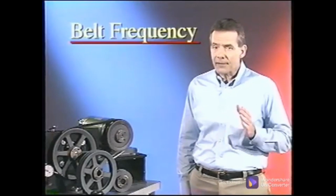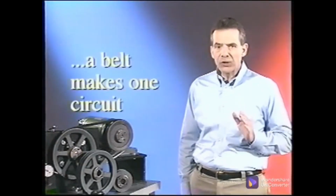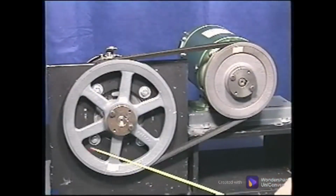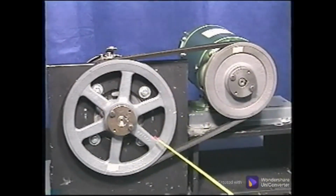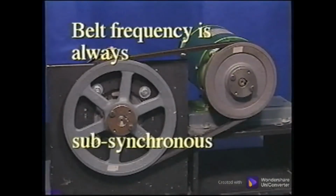This belt rotational frequency is usually referred to as belt frequency and can be defined as the number of times per minute that a belt makes one complete circuit. Since the circumference of the belt is much larger than either sheave, it will not make a complete circuit or revolution as quickly as the sheaves. Because of this, belt frequency is always subsynchronous energy.